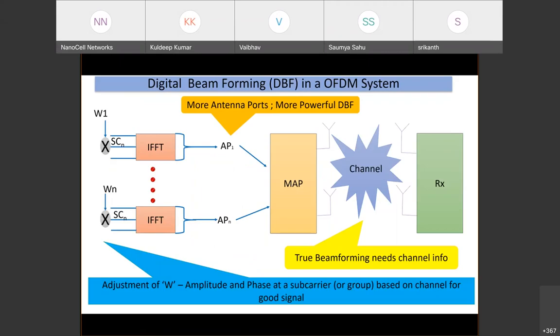Now, what we must understand is that whenever we talk about multi-user MIMO kind of systems in this OFDM context, remember that has to happen pre-FFT. So all multi-user MIMO related processing has to happen pre-FFT. This is important for some of you who might have listened to my colleague Devdas on ORAN implementations. You might have seen some splits where they do something in DU, something in RU. You might be wondering, why are they talking about all this complexity and bandwidths and all that stuff? Because there are certain implementation nuances.